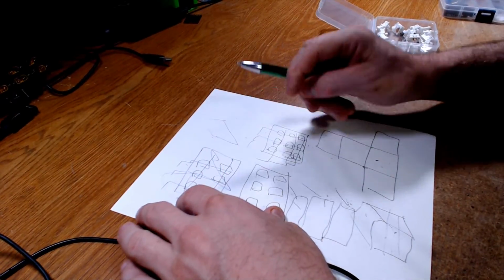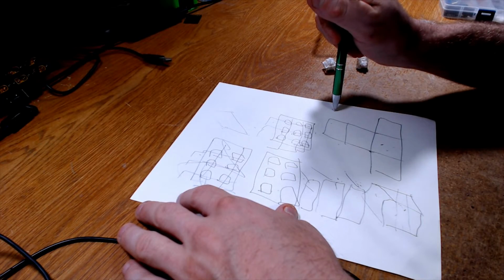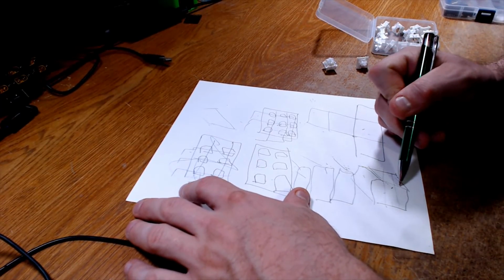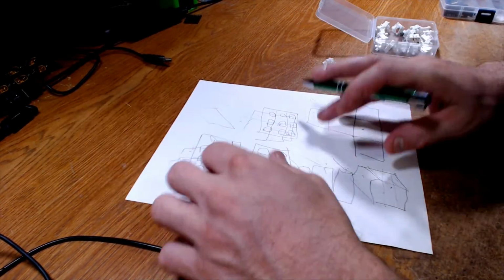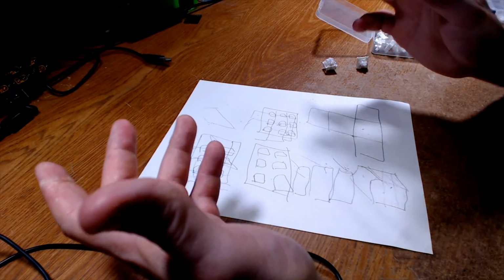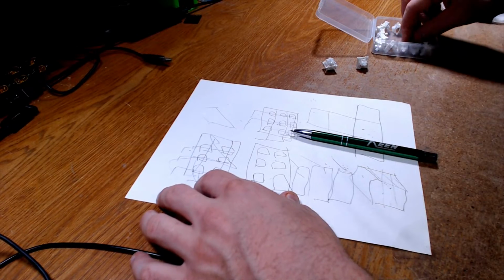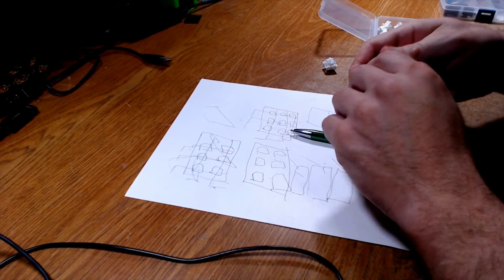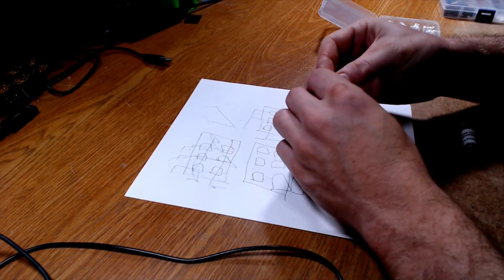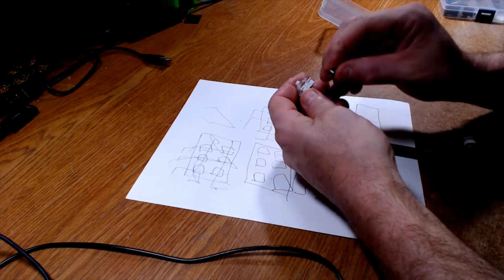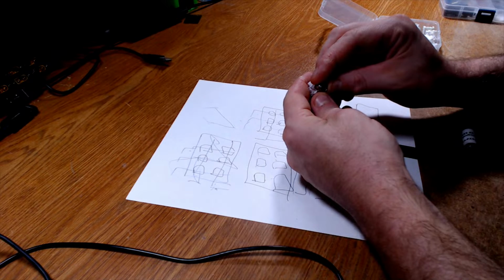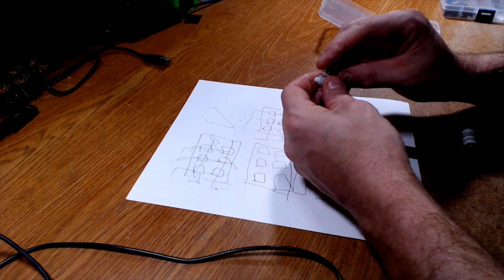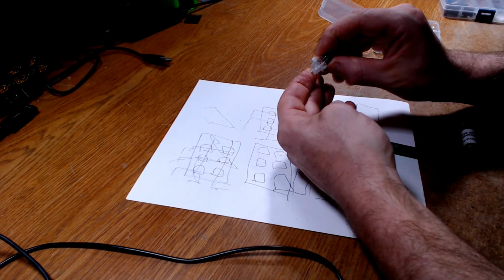So that is all the design considerations, I think. Is that everything? I guess the last thing I will mention is this whole sliding part. In theory, the sliding part, if I'm using PET, which I am, slides relatively well against each other, but let me actually grab one to demonstrate. These are my 623s, rather, not 608s, 623s that I use in a lot of projects. And as you can see, they're smaller than the buttons to begin with. So I figured if we use rollers, then that should, in theory, make it even easier, and they're not taking up extra space because they're smaller than the things going inside the 3D printed enclosure.